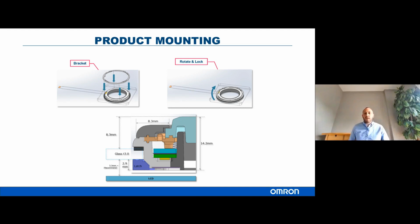And then underneath, we have the latch, or the bracket, that you would put on, and it would latch to the bracket, and you would rotate it and lock it into place. So the top part of our bash button, the bottom part of our bash button, and the glass, that is what equals a total thickness of 14.2 millimeters. And that will sit all above the LCD screen.